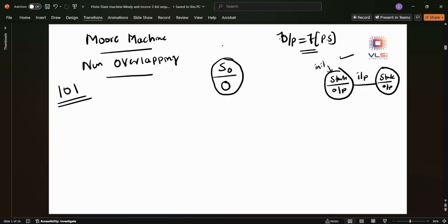And when it is 1, you got the first bit of the sequence, so it will go to the next state. You are not getting the full sequence; when we get the full sequence, the output becomes 1. So that's why the output equals 0 only. Okay, so this is 1. The two possibilities of S0 are completed.